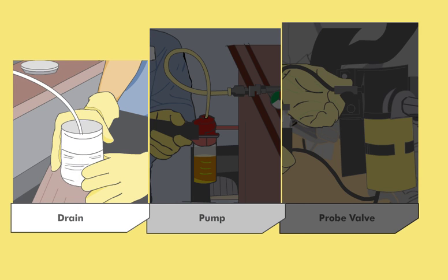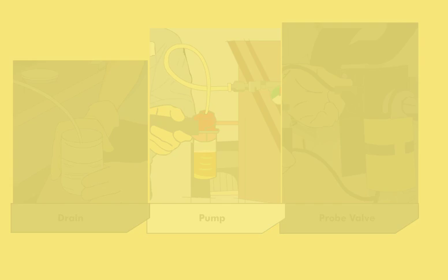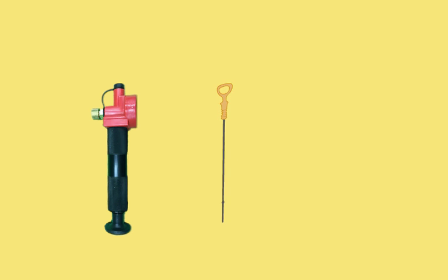To improve on the results from the drain plug, try a vacuum pump tool. Use the dipstick to determine how long your plastic sampling tube should be. By using the oil line on the dipstick, you will not pump oil from the absolute bottom, which would result in a sample with too much settled contaminants.